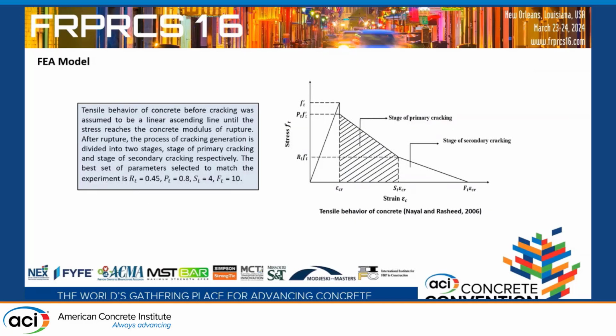After the compressive behavior is the tensile behavior of concrete. I used this model recommended by Nayal and Rasheed in 2006. Why use this model? Since with this model, you don't need to consider the bond slip between reinforcement and concrete. That makes the model very, very simple and avoids some convergence problems.